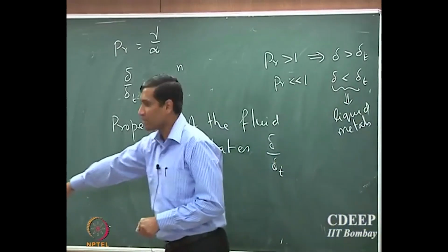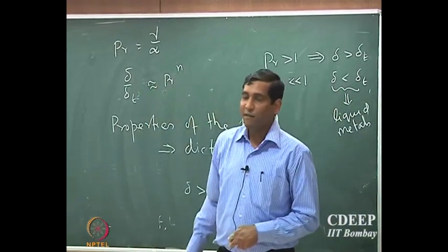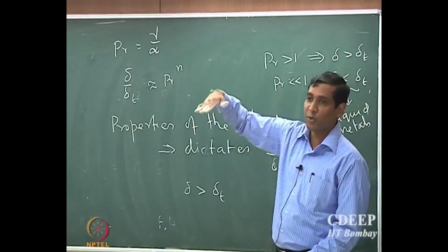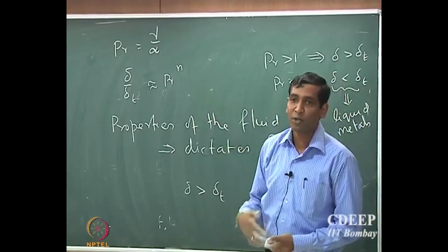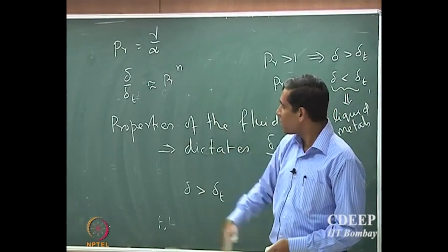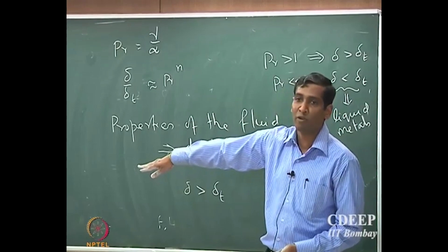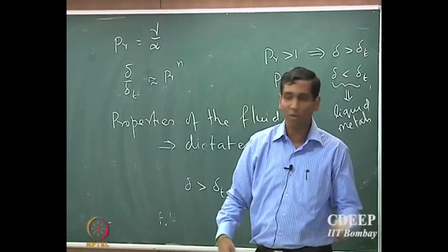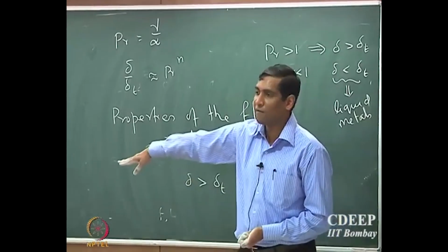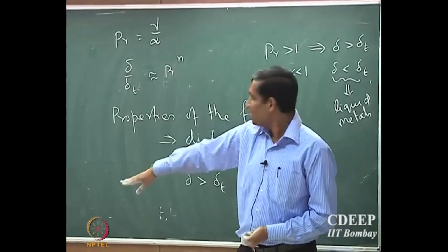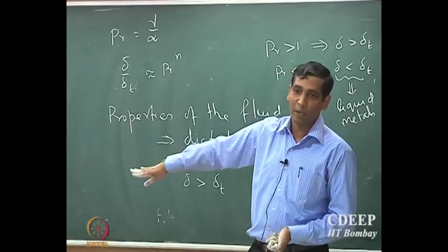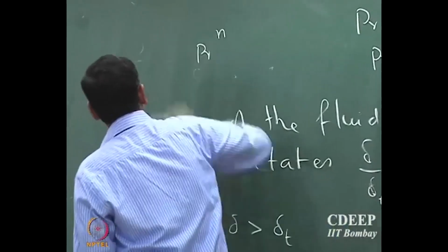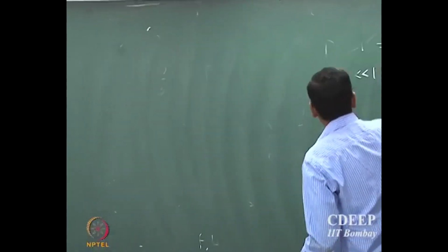So this 0.6 is a special case where if you have liquid metals in a very high temperature process, then the heat transport mechanism is slightly different, and therefore you will see that the solution falls out to be a different exponent, and we will see that in a short while, maybe not in today's lecture. I will give you the expression for the exponent n when Prandtl number is less than 0.6. Okay. So with this we can actually go and find out the heat transport coefficient.